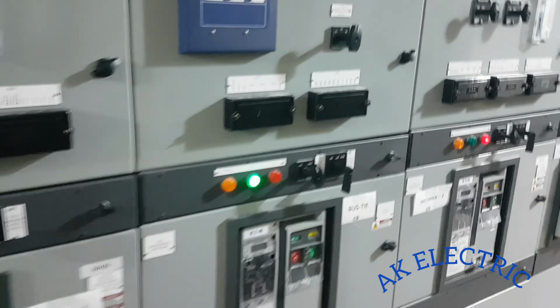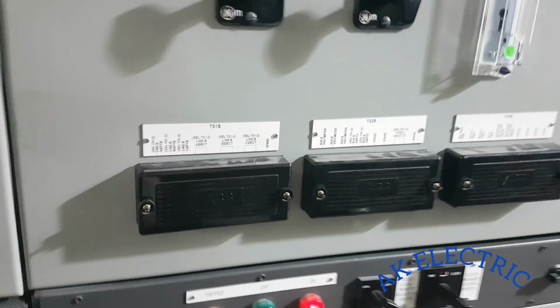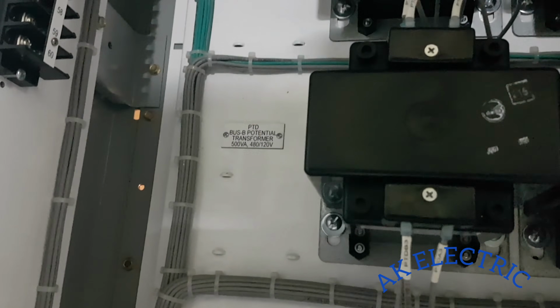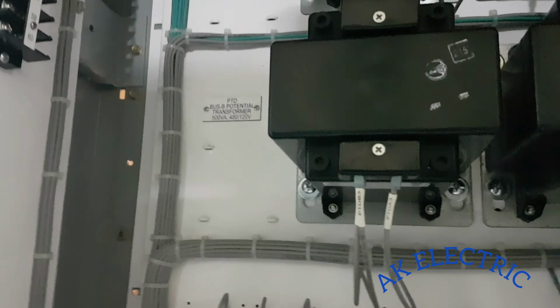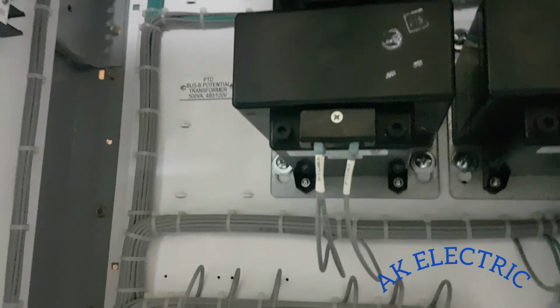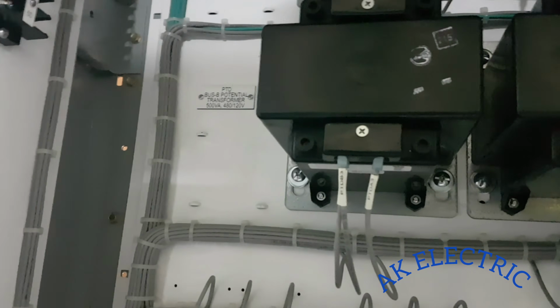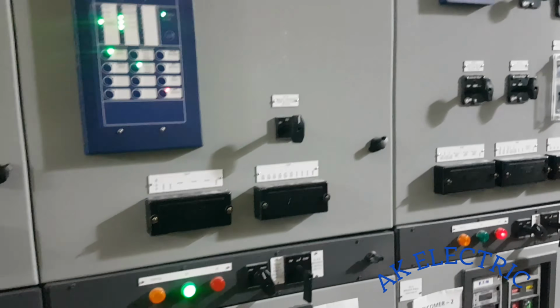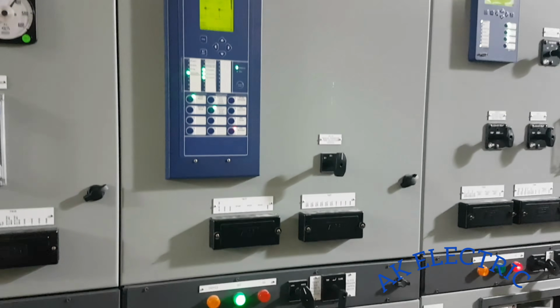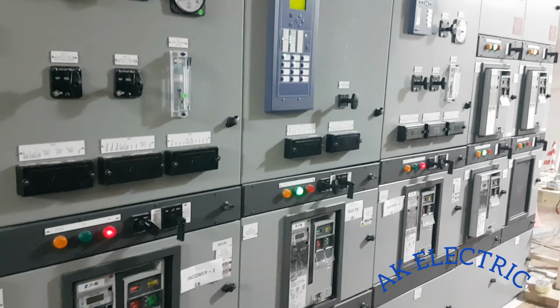I think I have to tell one thing. Before you perform this ATS function, you have to check your VT ratio. See here, my VT ratio is 480 by 120 volt, that is, the primary is 480 volt. This switchgear is 480 volt, but I am giving 380 volt. If you give 380 volt, this scheme cannot function and will not be checked correctly. So you have to make a correction in the relay, because your relay is programmed for 480 volt. You have to make this sync check for 380 volt. If you do that, then you can check this function. This is how the ATS function has to be checked.